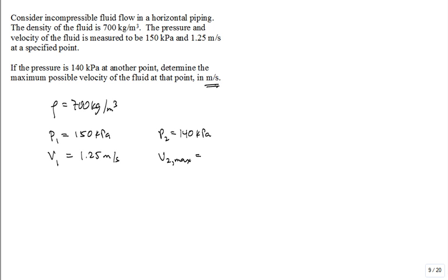There's a key word right here. Horizontal, delta Z is 0. So Z1 is equal to Z2, true? So let me just say Z1 is equal to Z2. Well, we would apply Bernoulli's, assuming steady flow. There's nothing to indicate transient. It's incompressible, along a streamline, blah, blah, blah. So what form of Bernoulli's makes sense maybe for this one? Yeah, we can do that one.